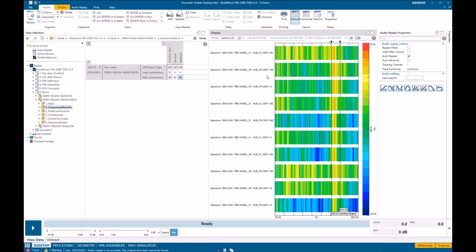So this gives me a very high level of information. And you notice front left, it's rotation in the X, front right, it's rotation in the Z. So different sides have different effects. Maybe that weight modification, the subframe design may not be perfectly symmetrical between left and right, and so that weight modification might be affecting the 2 sides a little bit differently.